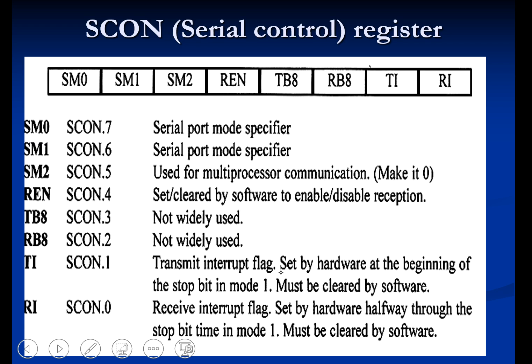Then SCON, that is the Serial Control Register, which I mentioned earlier, we will now see in detail. What is SCON? It is a bit addressable register used to set the mode in which serial communication takes place in the controller. The figure shown here gives the complete configuration of the SCON register. All the pins are also explained here.